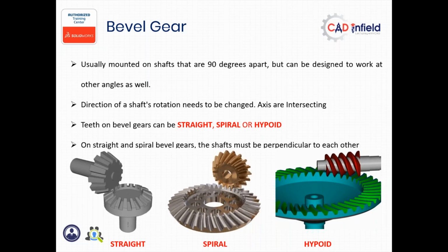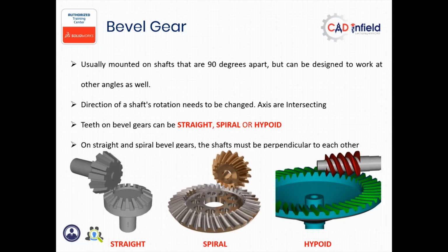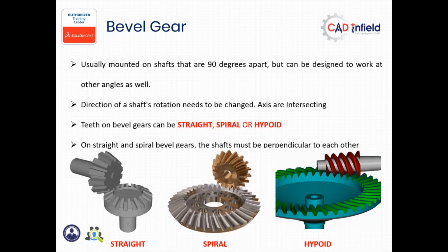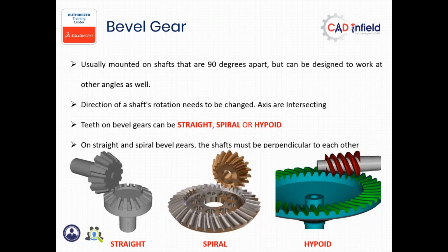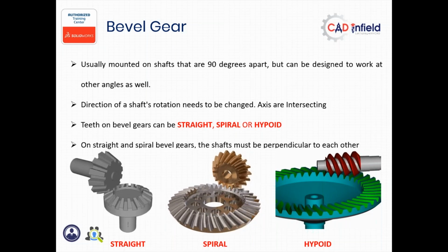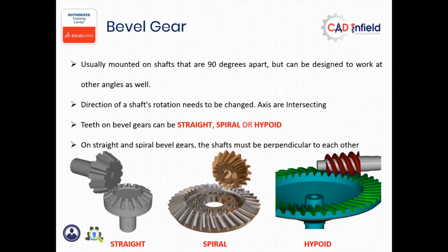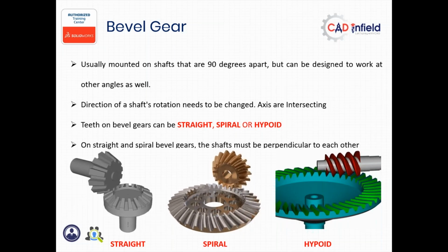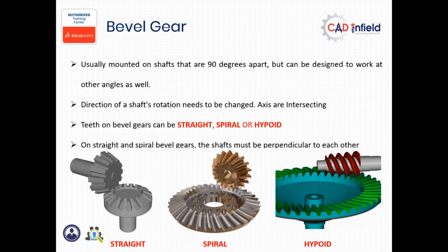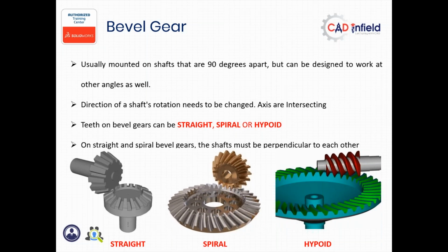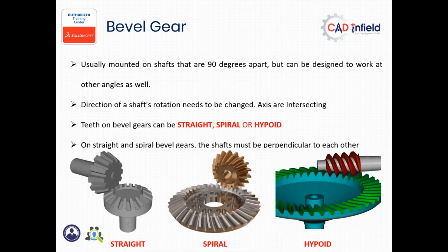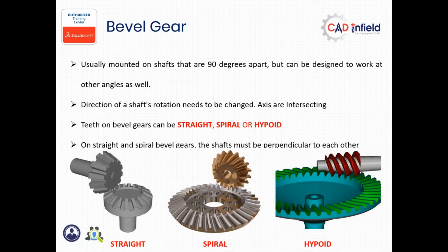In the spiral bevel gear, the shafts are perpendicular to each other. It will be a very balanced one, which has a point-to-point contact. Here, in the straight bevel gear, again there is face-to-face contact, which creates engagement of one tooth at a time. Why does only one engagement happen? Because unless the first tooth completes its engagement, the second tooth will not get engaged.